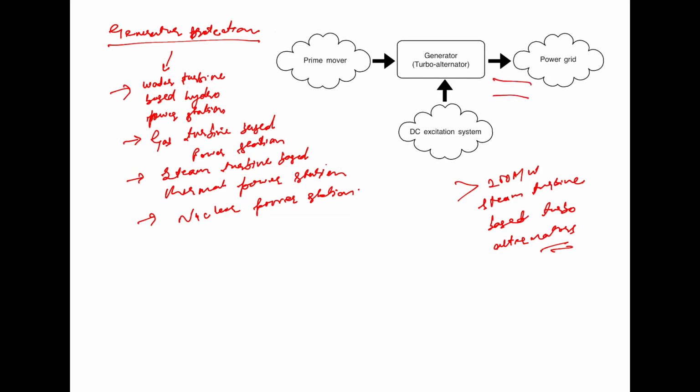Let us suppose that when the turbo alternator driven by the steam turbine is tripped, the following must be done. First, the steam supply to the turbine is stopped or bypassed.